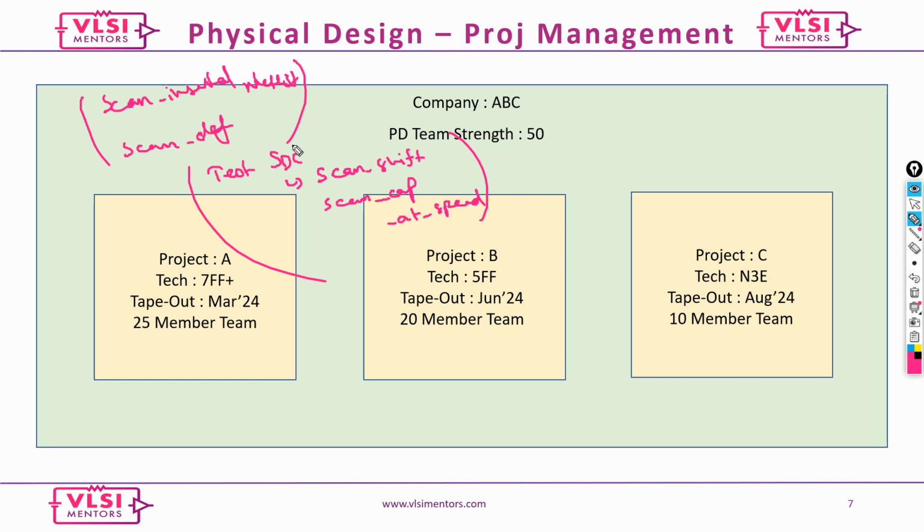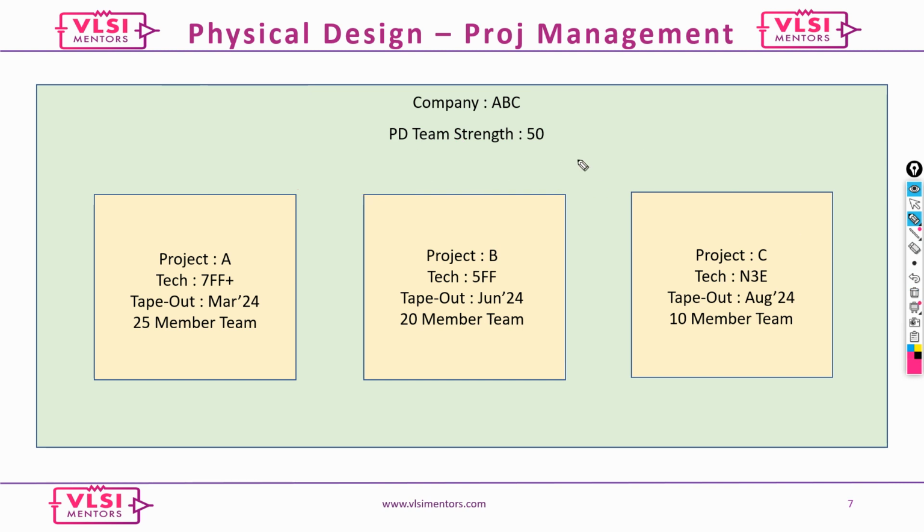And then we have how to check the VT percentage in ICC2. There is a command called report_threshold_voltage_group. That is a command that you can use to see the percentage of cells.